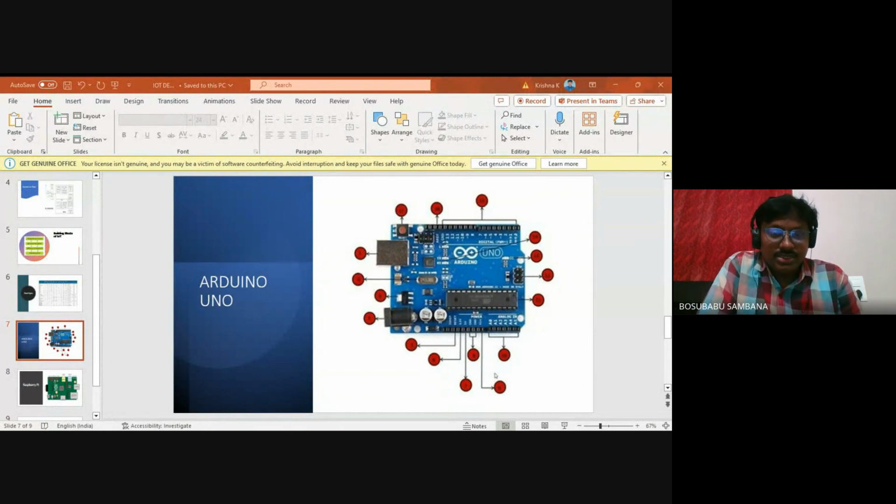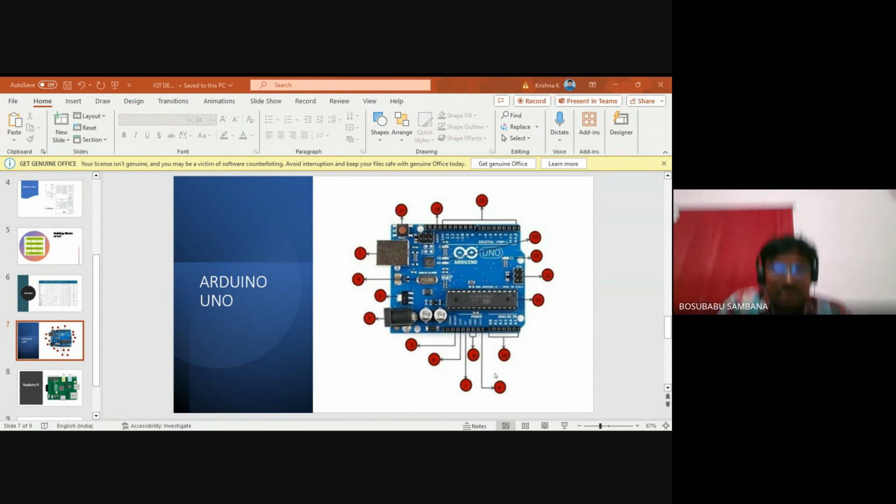Arduino board can be powered by using the USB cable from your computer. All you need to do is connect the USB cable to the USB connection. Arduino boards can be powered directly from the AC mains power supply by connecting it to the barrel jack. The function of the voltage regulator is to control the voltage given to the Arduino board and stabilize the DC voltages used by the processor and other elements.